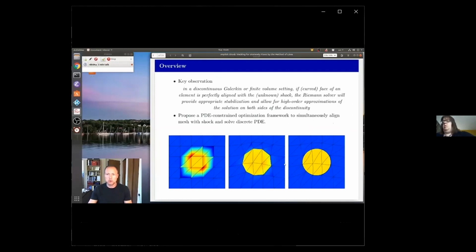We use discontinuous Galerkin methods, which naturally allow for discontinuities between the elements, not within the elements. So if you don't move the mesh, it's unlikely that a DG method is good for handling shocks and discontinuities. But if you somehow magically manage to align the mesh with the discontinuities, the formulation itself is very natural for representing this without any need to refine excessively around the interface.